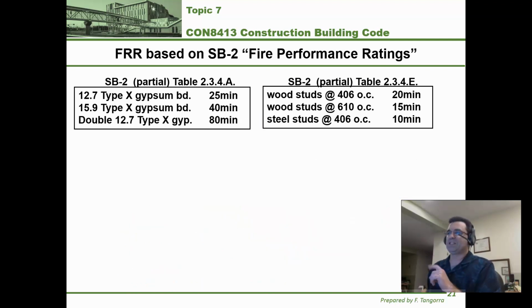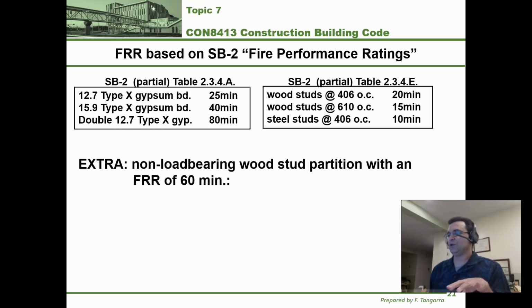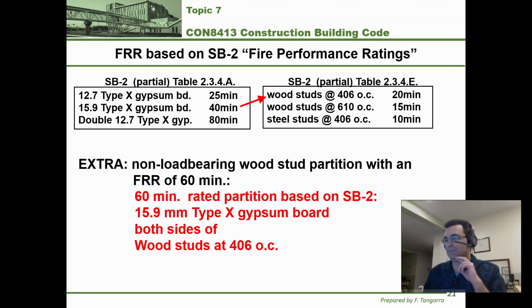Okay, let's try an extra example. It's not in your course notes, it's only in your video. Okay, and we're very close to the end, I promise. We're going to look at a non-load-bearing wood stud partition, and we want to achieve a fire resistance rating of 60 minutes, 1 hour. So I'm still using the same two tables because I want the bare minimum, okay? And it looks like that I can do it if I can connect the Type X gypsum board, the 15.9 millimeter Type X gypsum board, with the wood studs at 406 millimeters on center, right? That should work because that would give me...